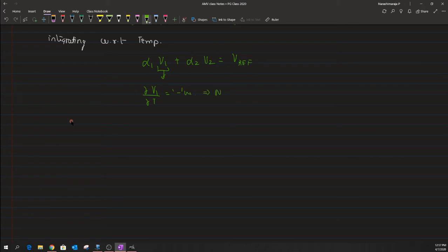So this exhibits a negative temperature coefficient, and when we analyzed the circuit that exhibits this kind of behavior, we found that the base emitter junction of a BJT structure, when it has been forward biased, exhibits a negative temperature coefficient, okay.